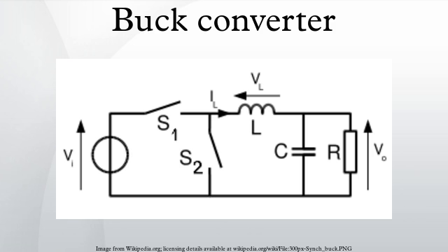The multiphase buck converter is a circuit topology where the basic buck converter circuits are placed in parallel between the input and load. Each of the N phases is turned on at equally spaced intervals over the switching period. This circuit is typically used with the synchronous buck topology, described above.